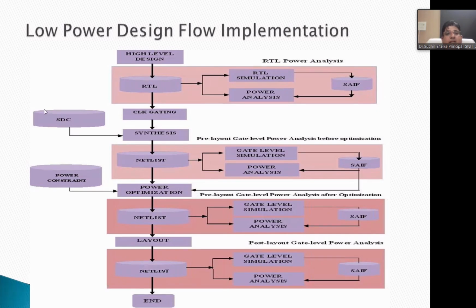So these are the Synopsys Design Compiler and the Power Compiler. Using the design compiler and the power compiler, you can target the estimated power of the design, and ultimately it is converted into the actual power which is required for the particular portable device.